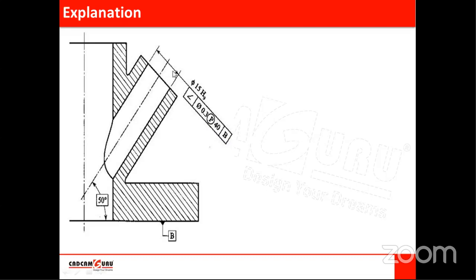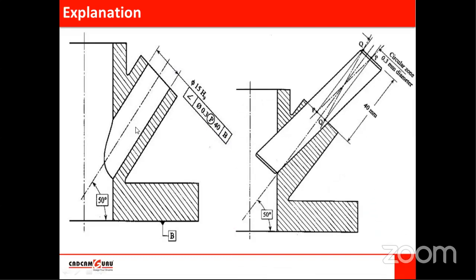So we can insert a pin here and measure the angle of this pin. We can mark the error in angle with the bevel protractor. We can attach this bevel protractor with this pin and get the actual deviation, right? So this is similar to perpendicularity. That's why I am not explaining more. You can get it easily.